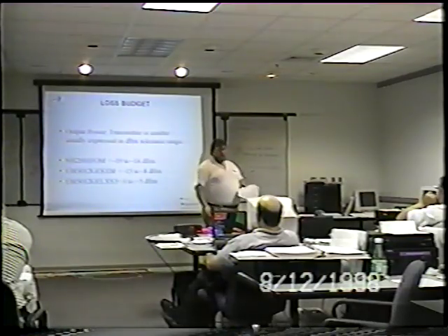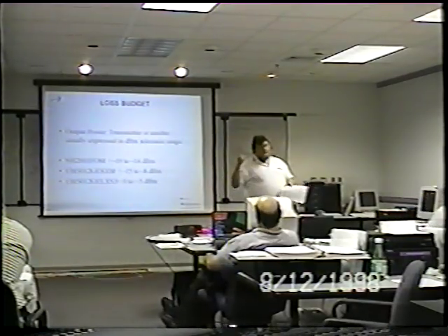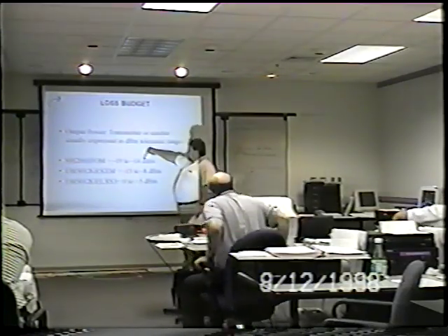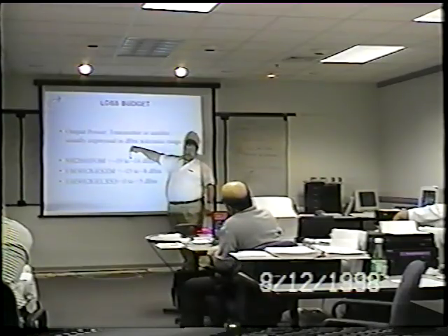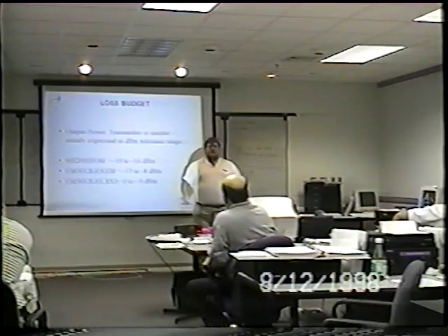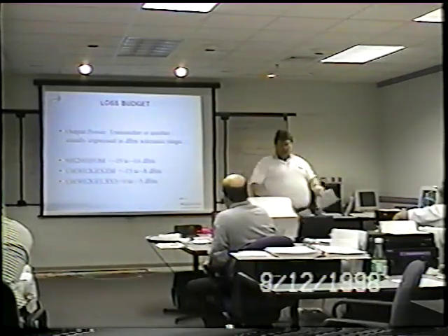is to use the lower number in all the pieces. Okay? So if you need an extra 3 dB that may be there, then you've got it. You certainly don't want to design to this figure here and find out that actual LED is only minus 17. So always design for the lowest output power range according to the sheet here.